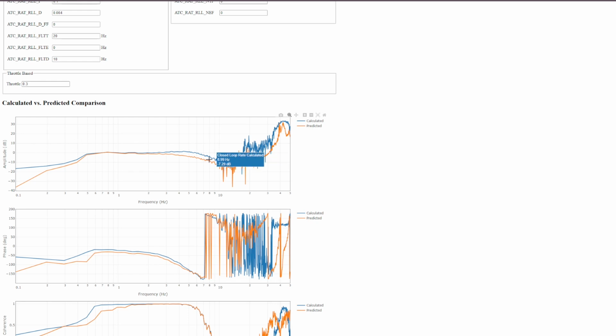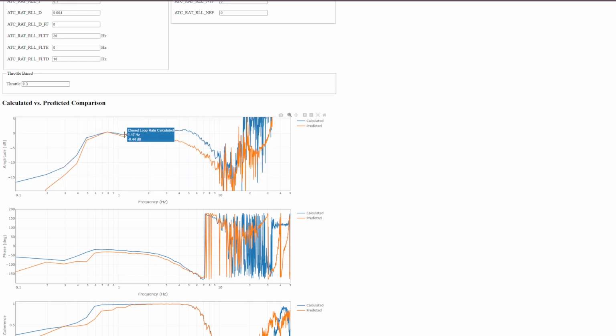So what this is telling us is 0 dB is 1. If this orange line sits on the 0 dB, it means we're getting the same magnitude out that we're asking for. And this phase here gives us an idea how far behind what we ask for the output is. So you can see at low frequencies, our gain's close to 1, close to 0 dB or 1, and we've got a very small phase. So it's slightly behind, but it's there.